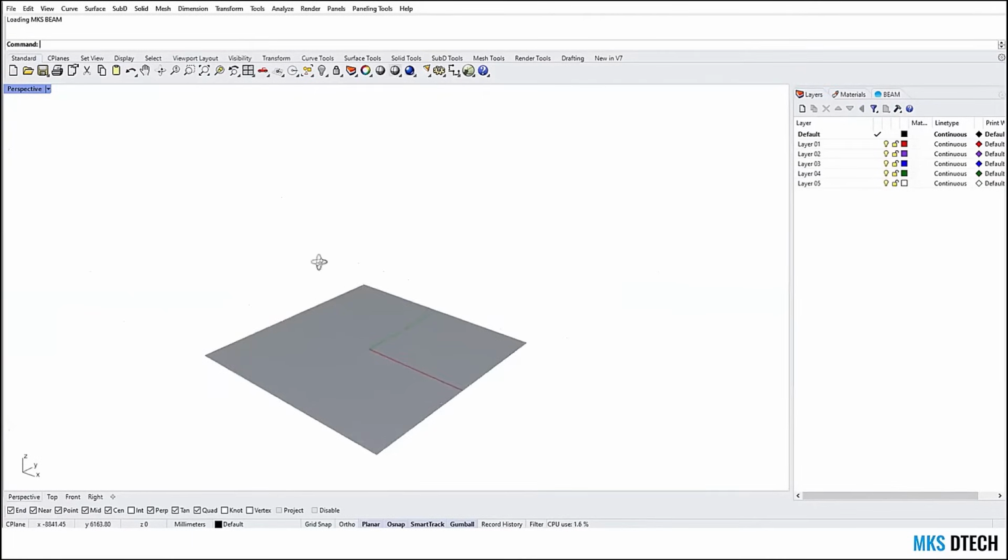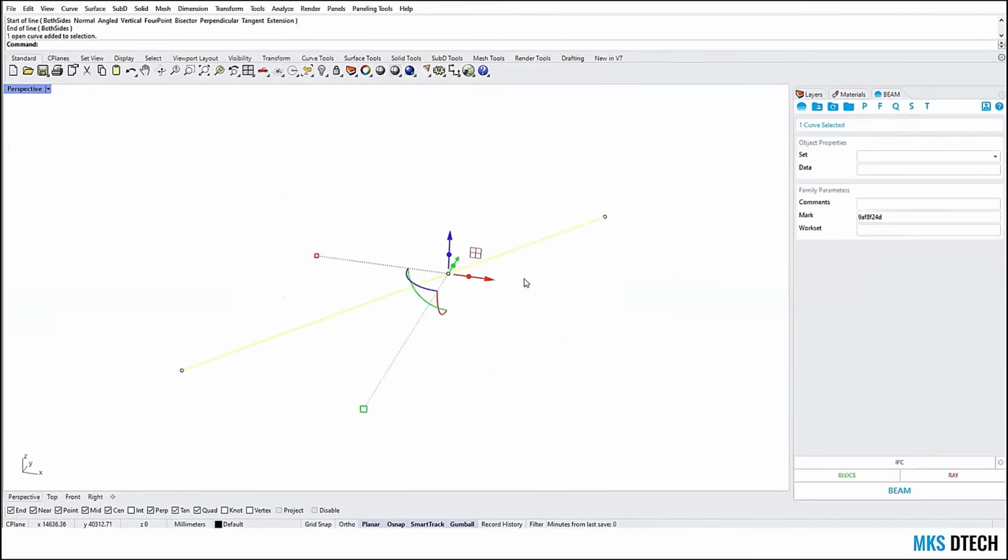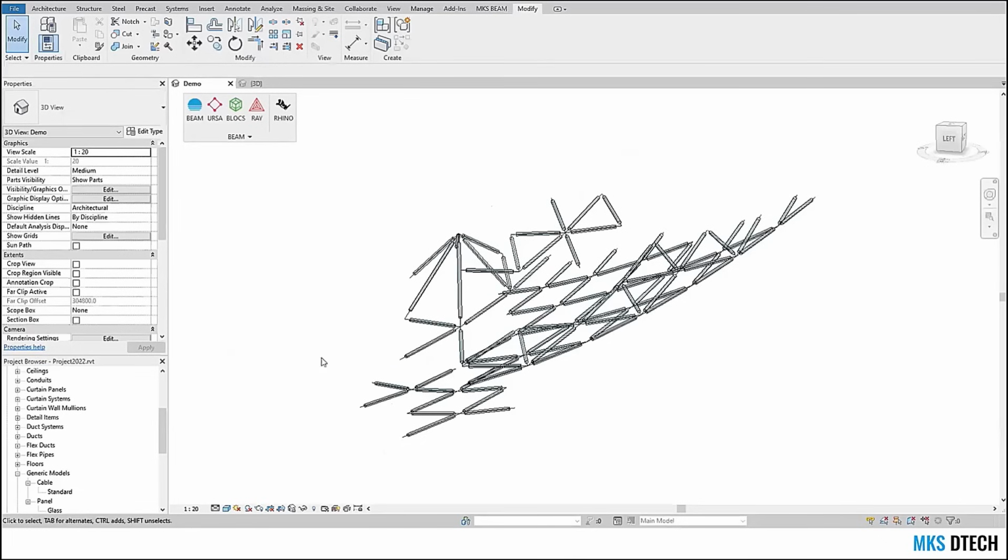This is a good point, because when we create a line and pretend this is our object, let's say a structural reference line, we can assign this as a beam or as a structural line, and we can use these to drive these adaptive components. If the adaptive components in Revit, let's go back into Revit and have a look at this.